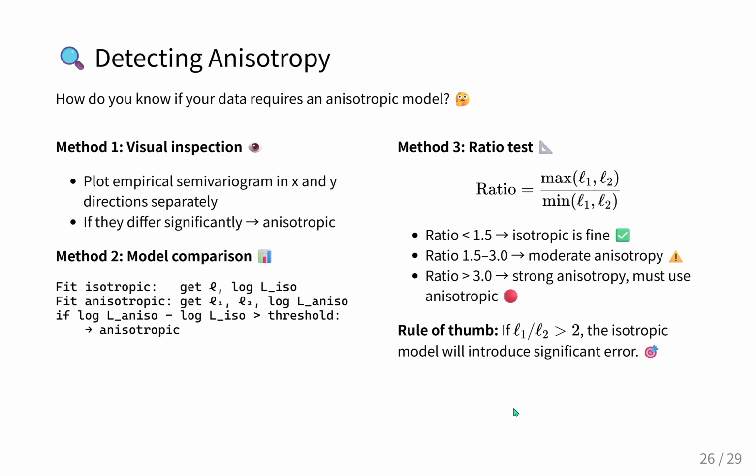You take your maximum correlation length, let's say the y-axis from the lithography scanner, and divide it by your minimum correlation length, the x-axis from the polisher. And that simple ratio dictates your entire modeling strategy. The author outlines clear golden rules.